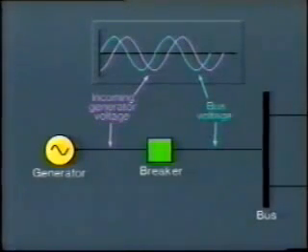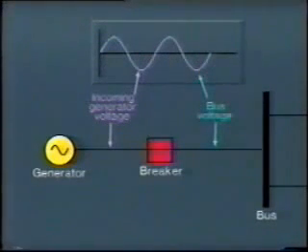If we closed the breaker in this condition, the generator would attempt to pull itself into phase. This could twist the windings and the stator core and create considerable damage. Of course, the great surge of power would be detected and the breaker immediately opened by protection devices.